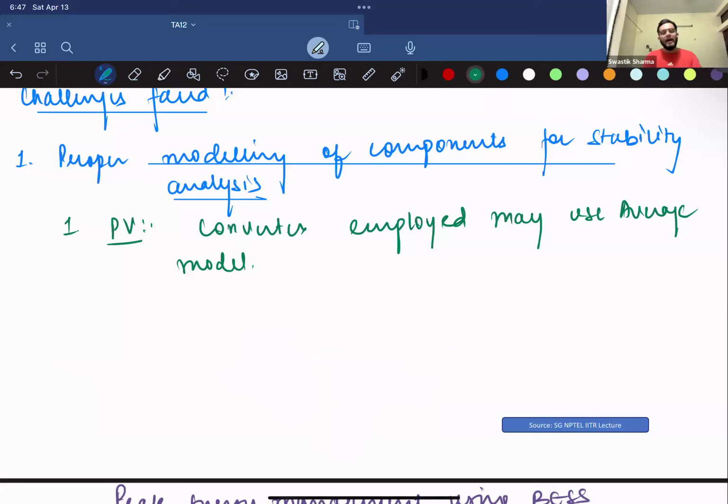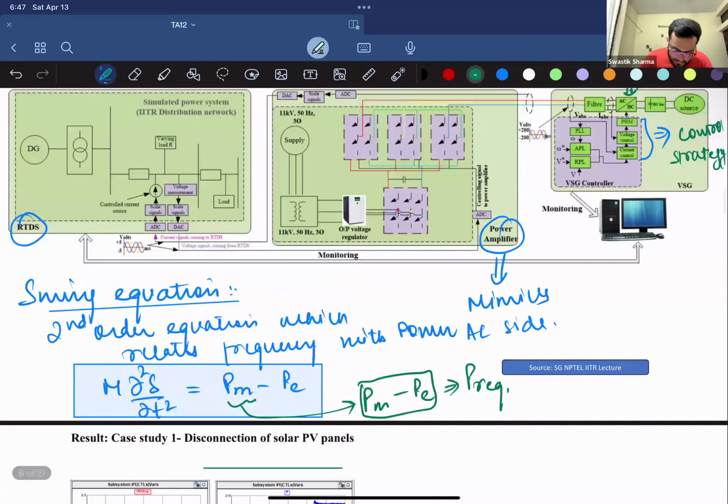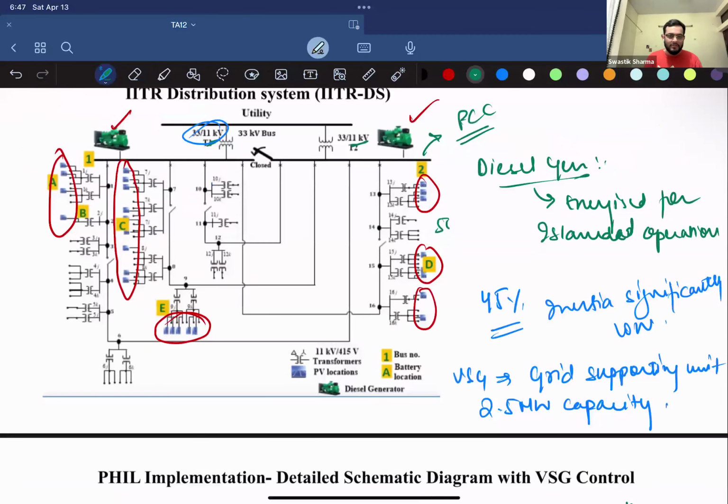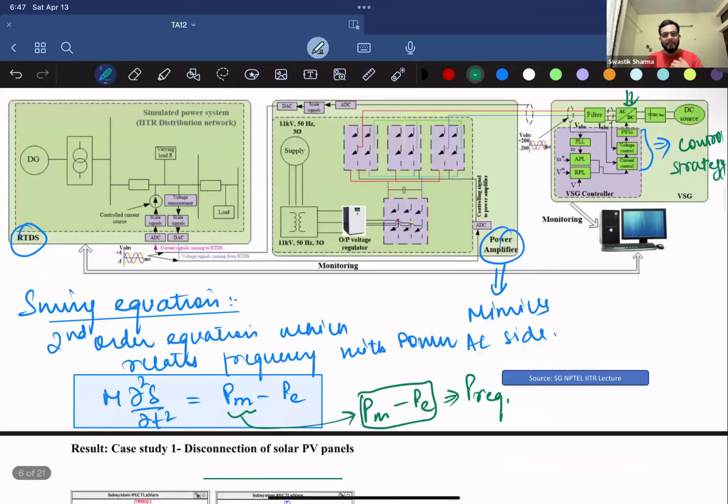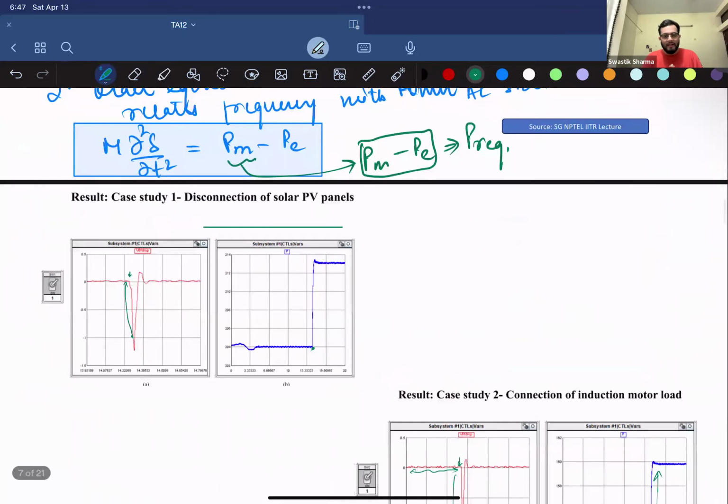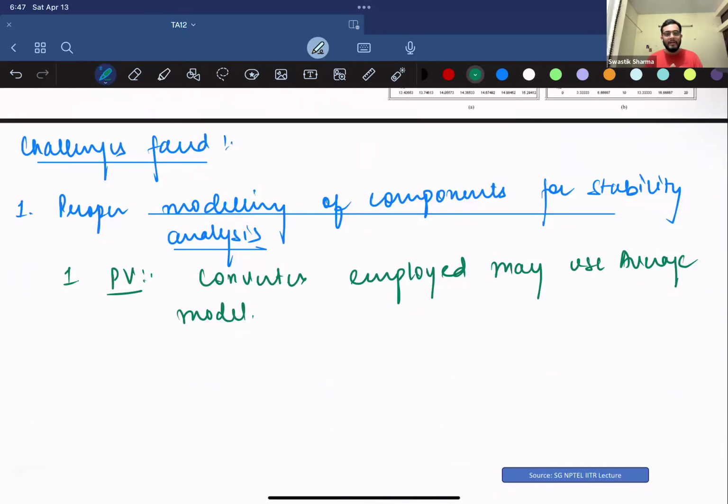Next, the other thing that could happen is that for voltage support, you need capacitor banks. Let's say that you modeled everything correctly, but still you're getting something missing in your distribution system. You may have capacitor banks, but that is something you wouldn't have modeled, or that is something that is required as well. So you need to be conversant with how your system would react by introducing certain components, as well as how they exactly behave, so that you are able to overcome the challenge of voltage support in case you are trying to model how your frequency would look like.